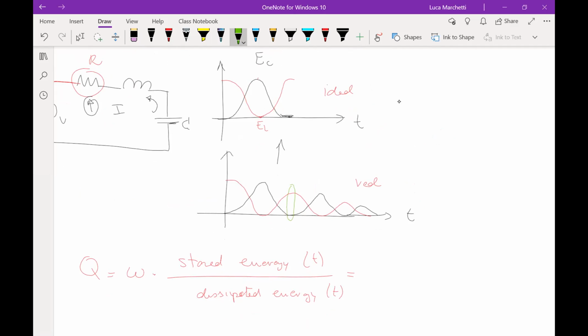At this point, for example, the energy of the inductance is maximum and the energy of the capacitance is minimum, practically zero. So all the energy in the circuit is just stored in the inductance, okay? This is the L in the inductance. So the energy in the circuit at this moment is just the energy in the inductance, which means the power in the circuit at this moment is the power in the inductance. And you remember maybe from ELEC that the energy in an inductance is 1/2 L I squared.